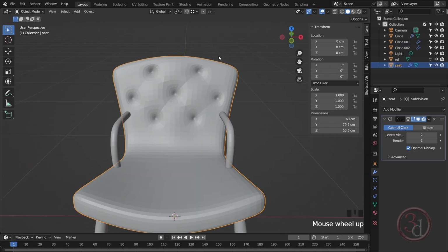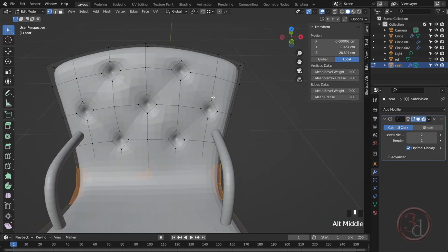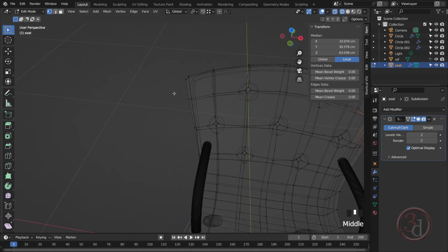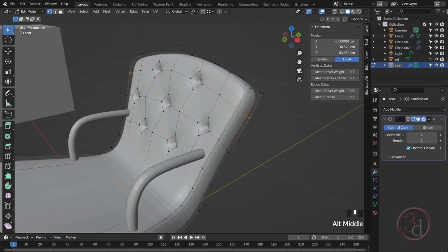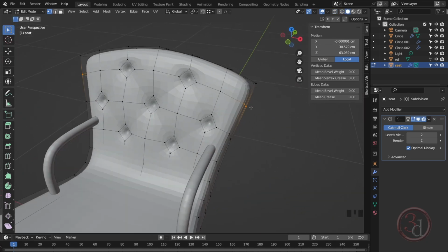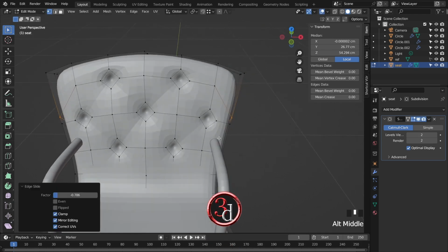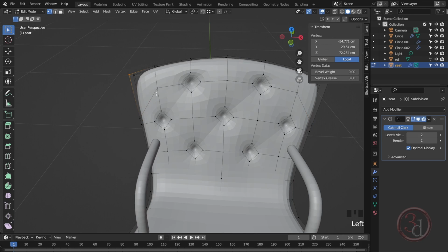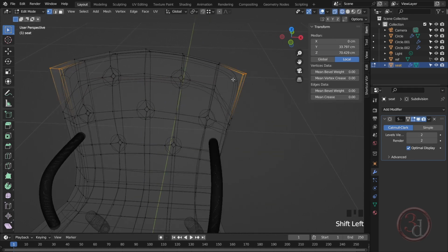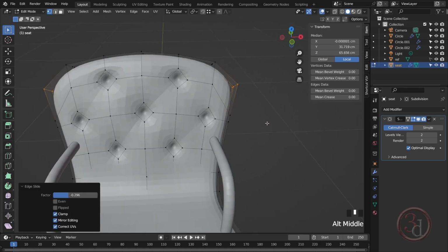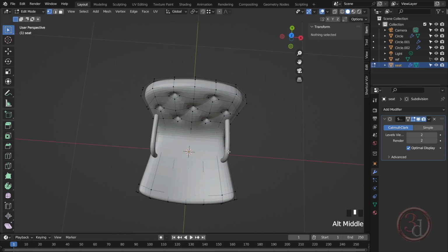Over here, I think this needs to have a little bit more smoother curve. So what I can do is select all of these from both sides. Okay, and I will slide them down. So press G twice, G, slide them down, and you can see the shape. Yeah, same thing I'll do again with all of these selected. And then I'll press G twice again, G. Okay, this is looking fine.